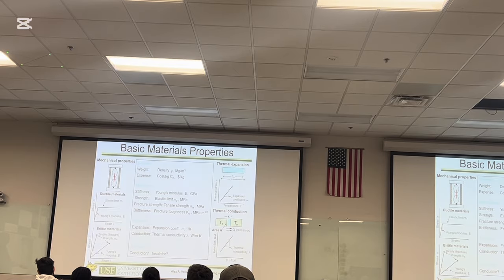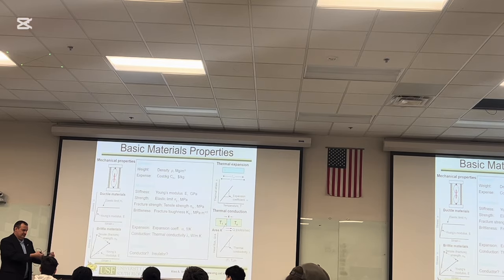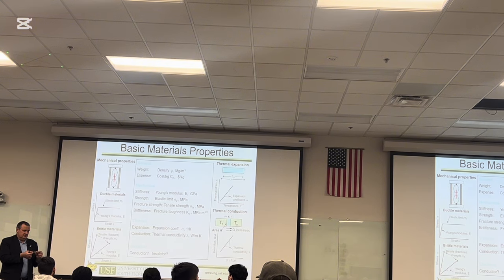Mechanical, we're going to have a separate lecture on that, but I built a machine. I built a portable tensile machine for specific applications. And to test the mechanical properties, what you need to do is pull. Now I came in a little bit more prepared, so here's the thing, you can pull. I'm applying the force, and as a result of applying the force, I get the displacement, right? Okay. So the force can be converted into the stress, right? How? Anybody know?